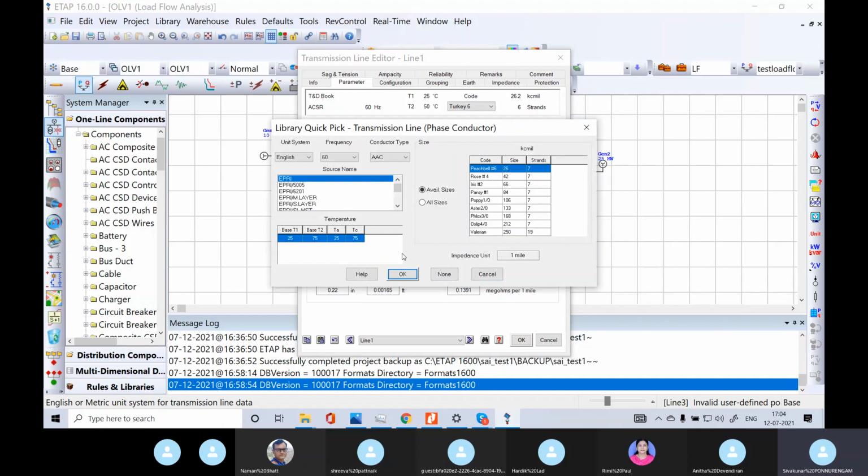Similarly, each and every company is going to upload its conductor data in the file. As in PSpice simulation, each IC component manufacturer develops the PSpice file for the simulation and uploads it to a common network, a common source. Similarly, all the standard conductor manufacturers develop the conductor resistance, reactance and every value, and load it commonly. That data can be inherited by the line.